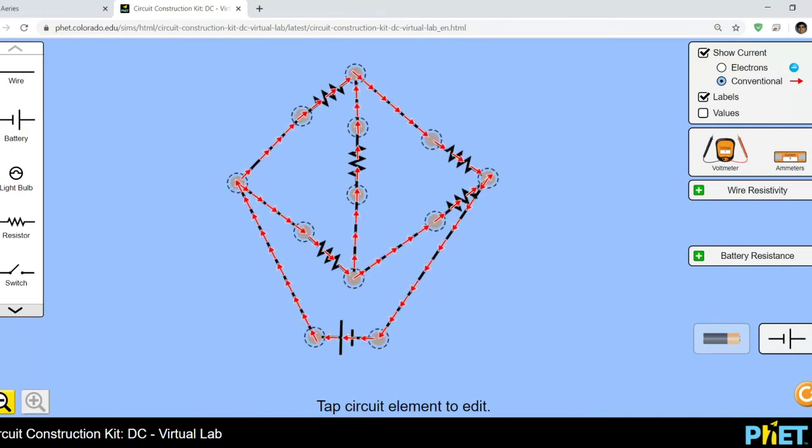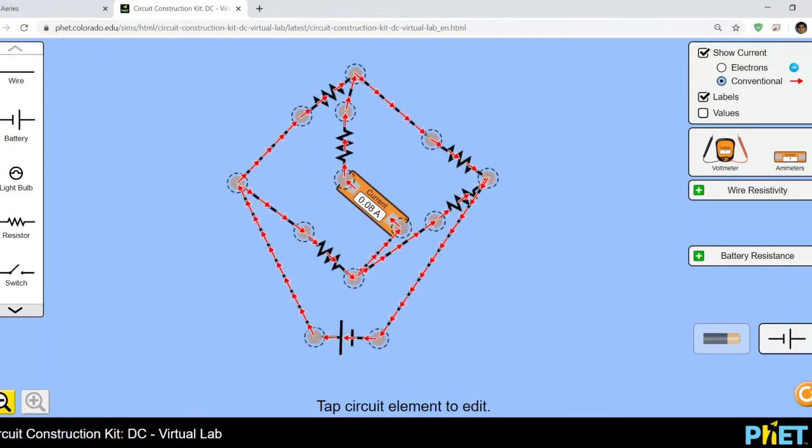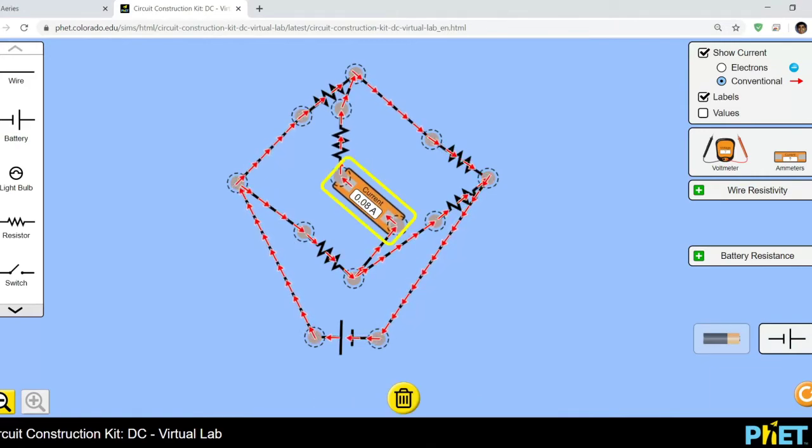Okay, so to make measurements, again, you would have to make breaks. It doesn't matter if you break it in front or behind. Looks like it's stretched out. And be careful because it's only going to give you one sig fig here. So take the values with a grain of salt. Use P equals IV. Don't use the other power equations. Use P equals IV for power.